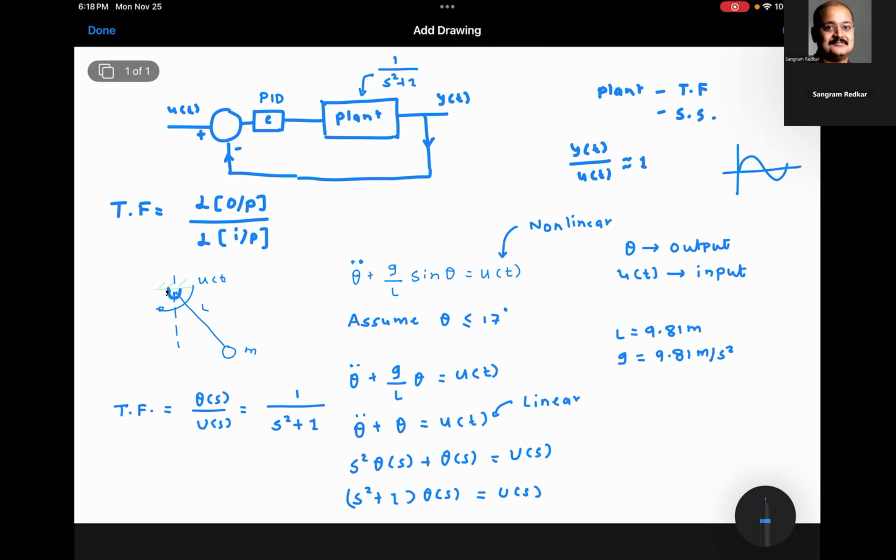And the beauty of it is, imagine that you have a system something like this. The linearization, the linear approximation, is valid near the operating point. For example, if you are here, this linear representation is okay, but this linear representation fails if your operating region or operating point is somewhere else, because you can't fit a straight line and you need to find a new linearization. Everyone understood this?